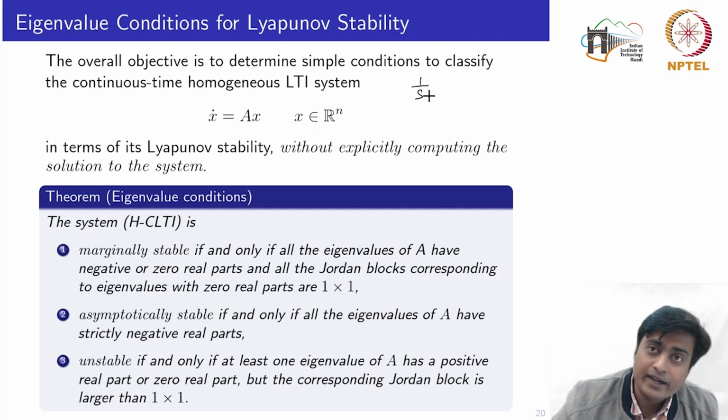And for any initial condition, the response would become constant. So what does it mean? If I am using the integrator with respect to the initial condition, then it would be bounded, right? But it won't be asymptotically stable because the response will never go towards 0.